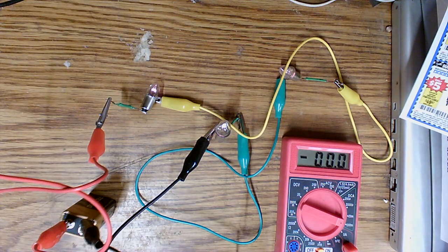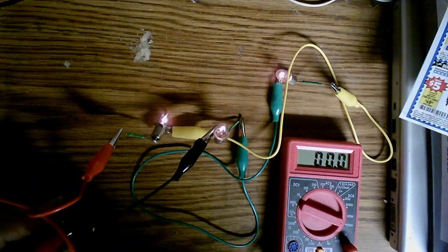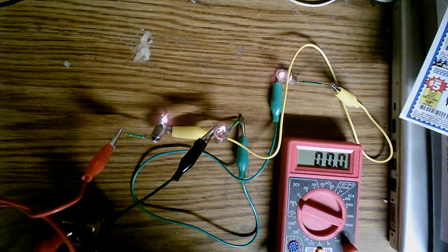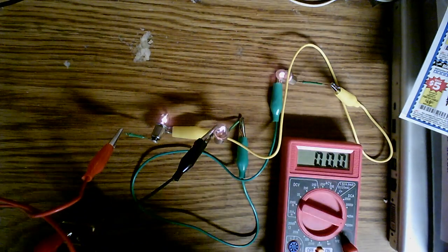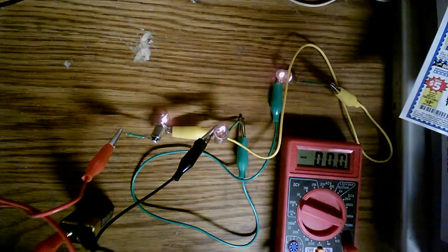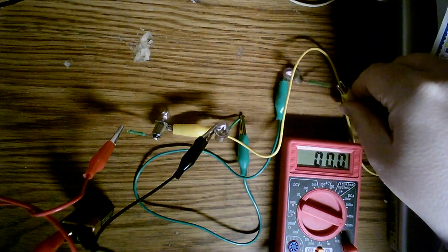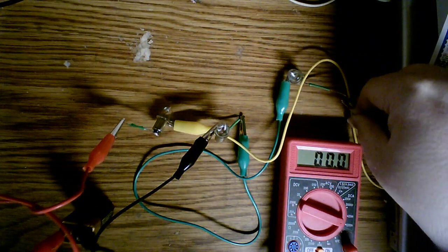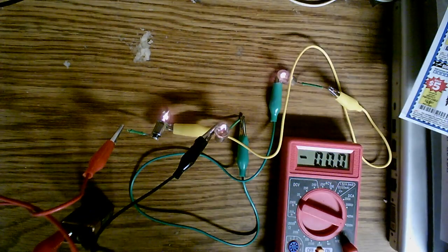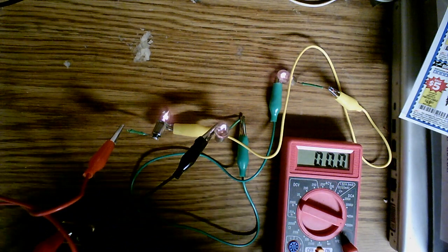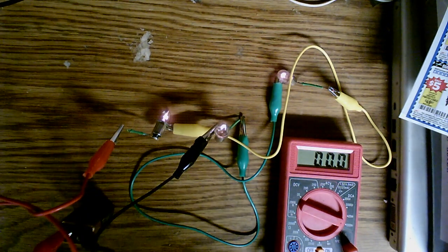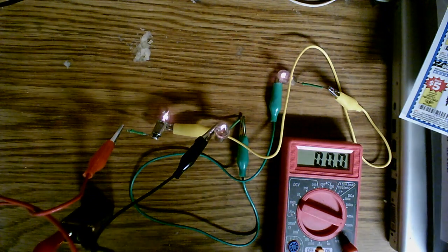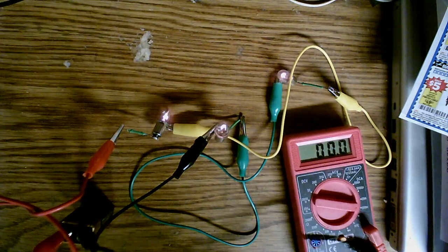Now you'll notice that they're very dim here. Okay, there we go. So when we hook this on, you can see that all three lights do come on. Now, one thing I forgot to mention earlier is if at any point in time we break the circuit, take one of these off, notice that all the lights go out. Reminds you of the Christmas lights, doesn't it? Another thing we're going to notice here is that the lights are very dim as compared to what we saw in the Ohm's Law series, where I just had the 9-volt battery hooked up and running into a single light.